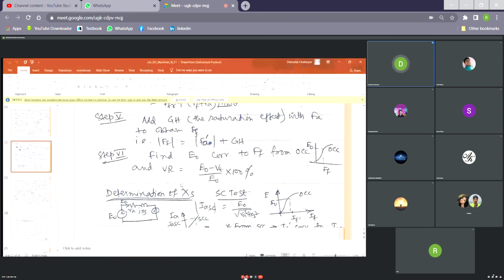And there are skin effects, because of the higher diameter of the conductors, so the skin effect can become significant. So you can multiply the obtained value by 1.5 to 1.6 even. It depends on the machine.